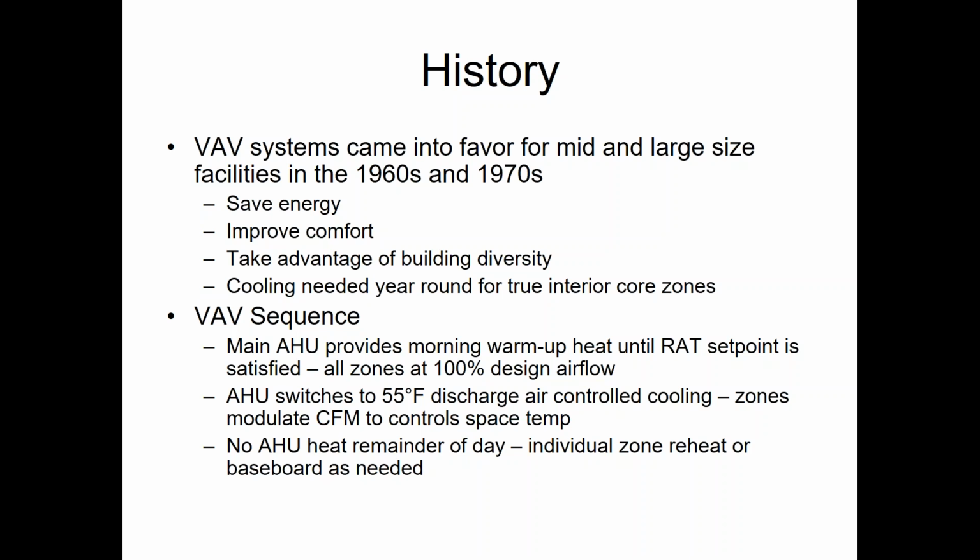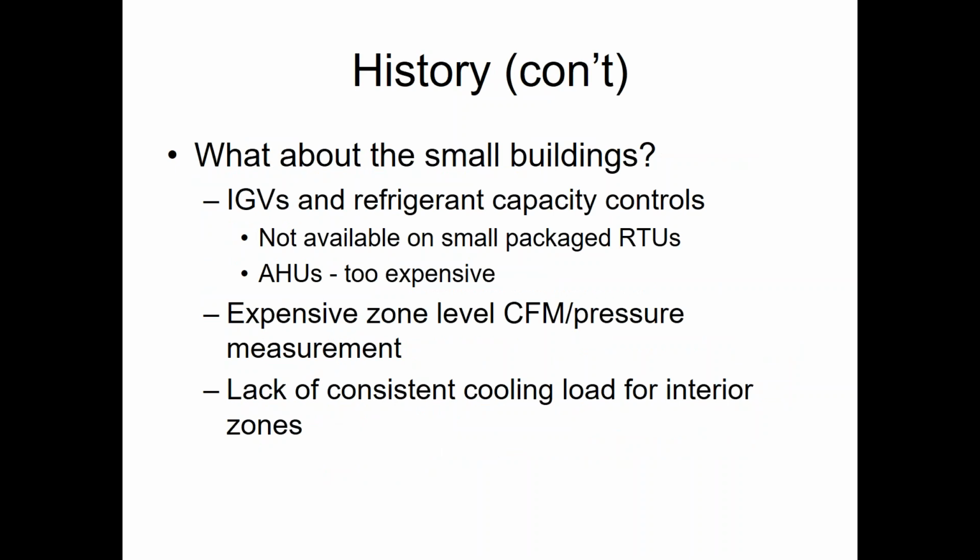On a small building that doesn't need cooling at all in the wintertime, it's going to be a problem. And you're probably not going to want to put a traditional VAV system on there. You're either going to want a modified VAV, or you're going to want to go to VVT, or a modified VVT. The two extremes have come much closer now in the past 10 years than they've ever been before.